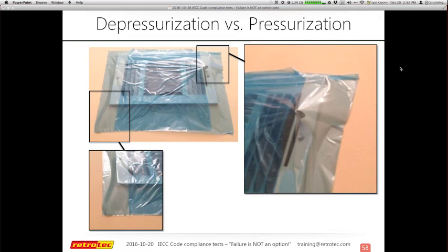If you did them and find out that you're a difference of 70 CFM, clearly there's a problem somewhere. Something you're either pressurizing or depressurizing is actually allowing things to move or close and open up. So it's a great way to confirm your results, especially if you're doing some kind of rough-in test, because you don't want to open up drywall again. For those of you that are doing the depressurization, this is common for both systems, the rings are actually inside the flex duct. You can no longer see the rings, so you keep track of what you have inside the flex duct.